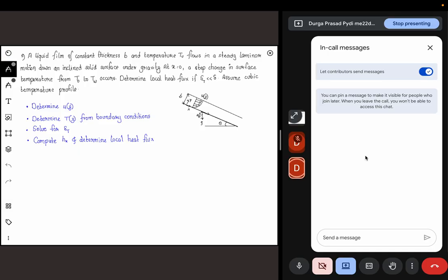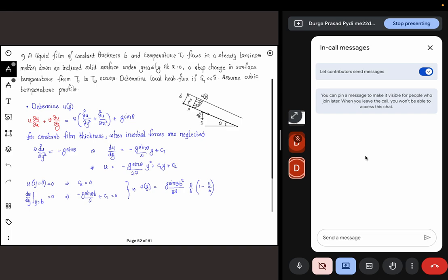You start with, again, the same differential form first. So we will take the momentum equation. So now I have my momentum equation as follows, x momentum equation. So I'll have g sine theta term additional here. So the pressure term is not there because here there is no pressure gradient imposed. Essentially, it is again a flat plate, so we don't have anything of that sort. So this is my governing equation.